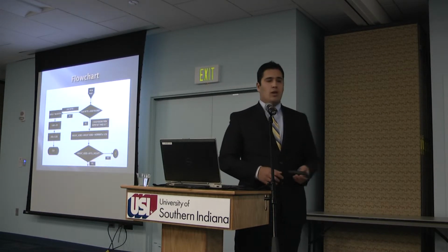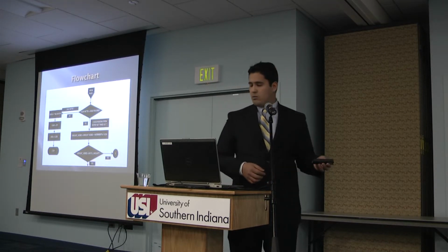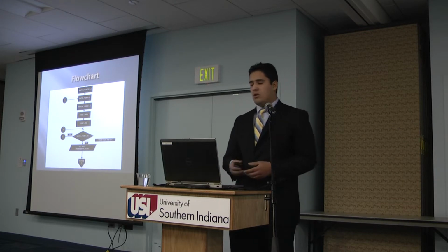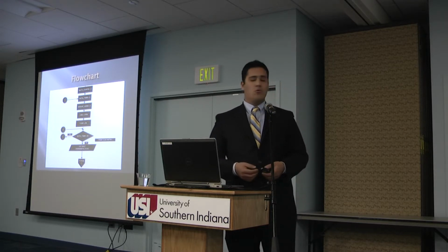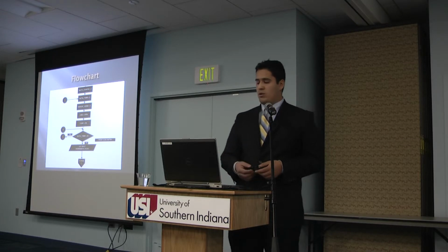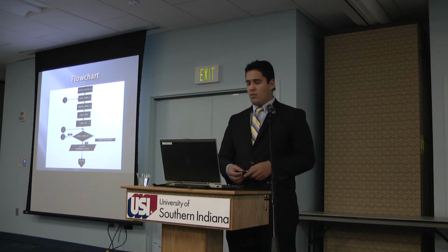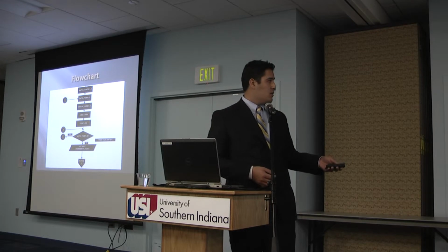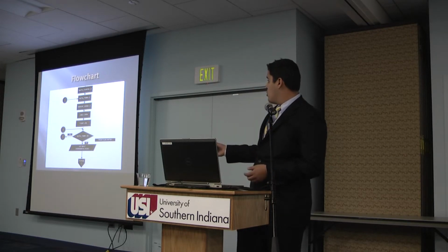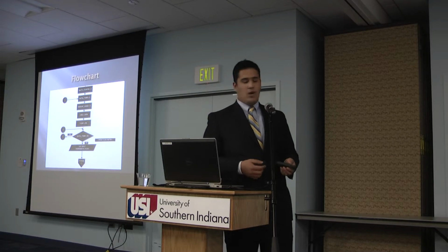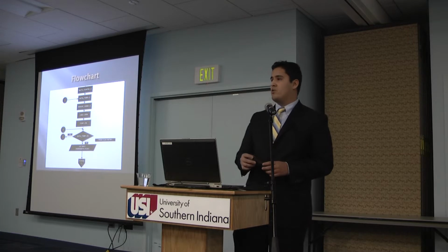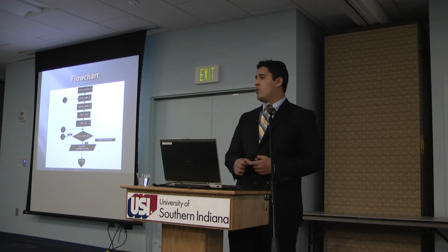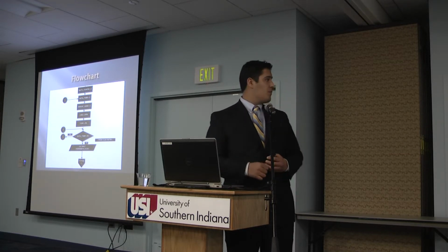From that, we start with the initial conditions. We have the batch counter, my apologies. Batch counter equals 0, batch timer equals 0. The amount added will be 0, and the lines will start opening, and the pump will start in order to start pumping the flow. We ask the timer: if the timer is equal to 60, we move along. If not, we get the input from the flow meter, which will also prevent overdosing. That's kind of like a backup plan in order to have a much more stable system.